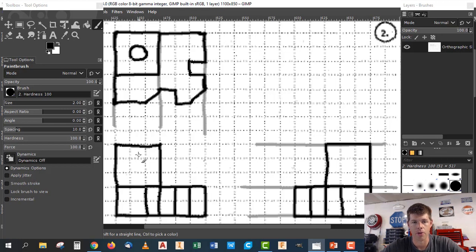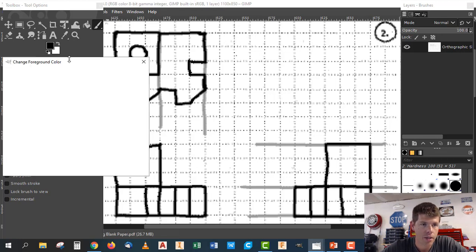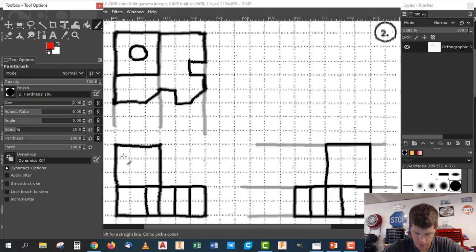And so I think drawing them with a pencil is the best way to start. So let's switch and finish this. Let's go to our red lines, which are the hidden lines. Thankfully, the only hidden lines we really have on here are due to this hole. So I'm going to go here, and this hole goes all the way down through the part. So I'm going to go here, and I'm going to have a hidden line that goes all the way down